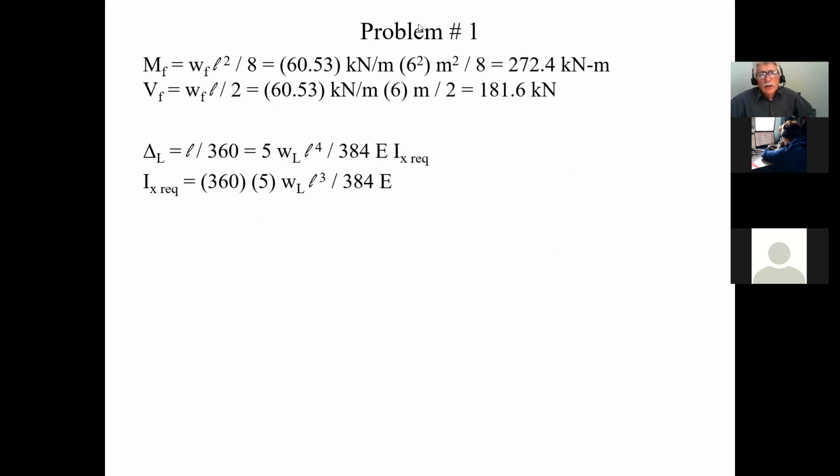And I hope you realize that in steel, you'll start seeing this more and more: when we have a wide flange, it can even be a C like this, okay? Wherever the flanges are, the axis that is perpendicular to the flanges is always the XX. They call this in steel, and therefore this is always your strong axis. And then this one here is your YY. They call that the weak axis. In other words, the moment of inertia about the YY is smaller than the moment of inertia about the XX, and that's why they call it the weaker axis.